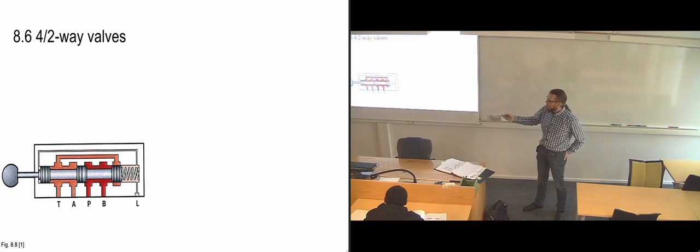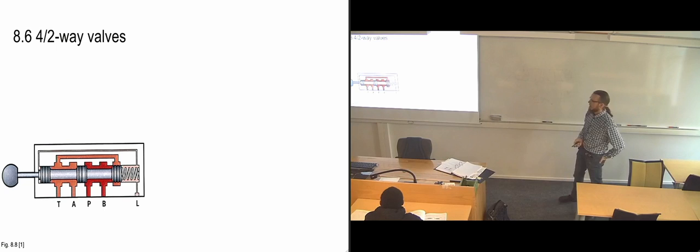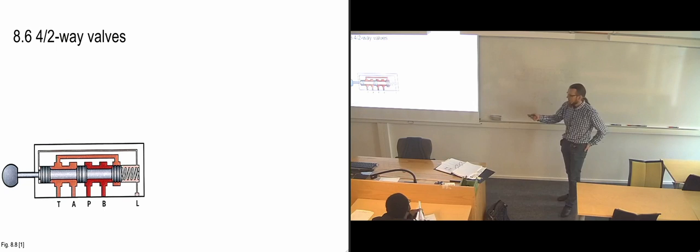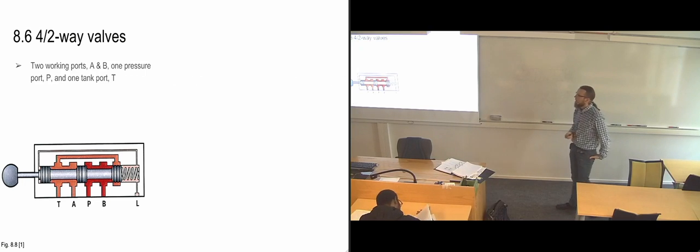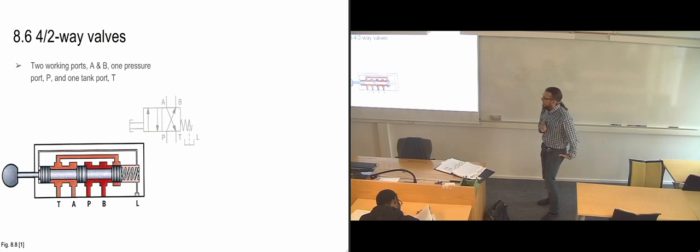So you really don't want pressure having the chance of escaping in here and coming to the other side, to the spring chamber, basically, because that's going to interfere with when you're actuating your valve. So that's why we have a separate leakage line for these.